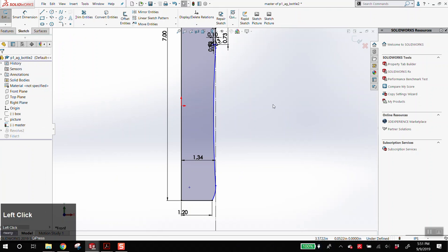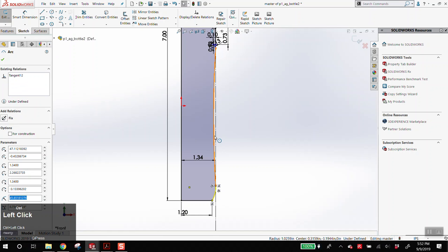It's not, but you can make an argument that there's a way that designers use SolidWorks and a way that engineers use SolidWorks, and for sure there is a little bit of this design push and pull in SolidWorks of how it looks. So again, just to reiterate, think about what variables you want to play with. A good rule of thumb is, like Anastasia said, something you're unsure about how it looks, leave that open as something you can drag, but you can define the overall width because you know what that is. So define the variables you know, leave the variables you don't know undefined, and drag. You can then play with them visually to see what they look like. But that's, again, where relationships like making these tangent becomes important.